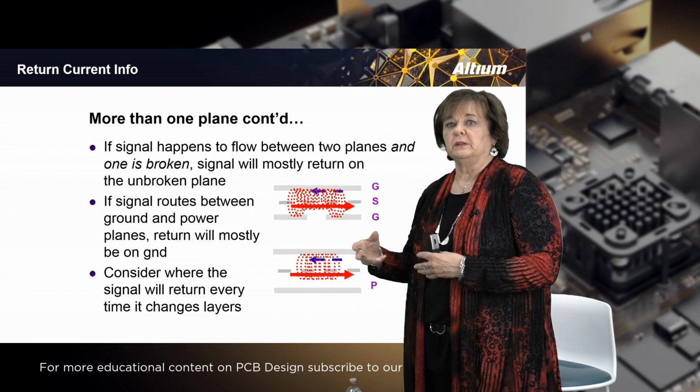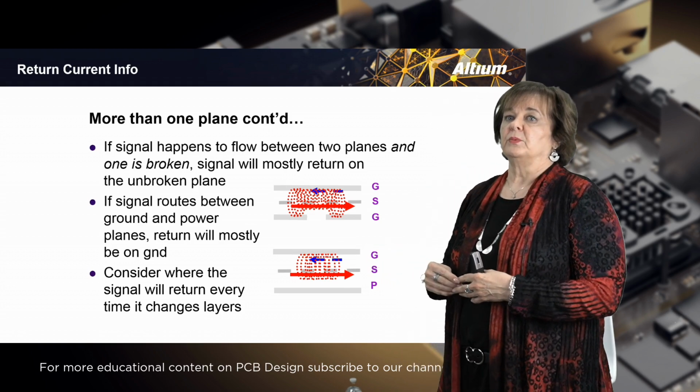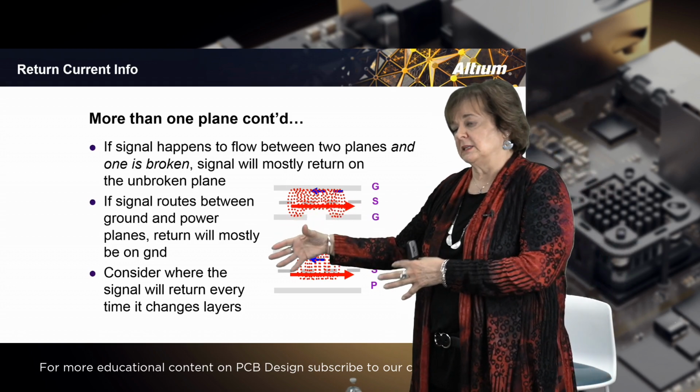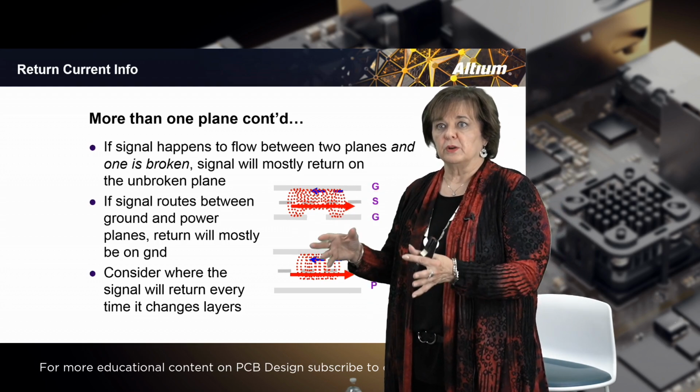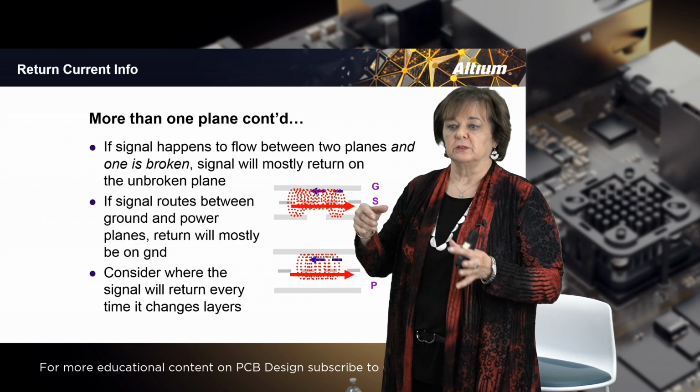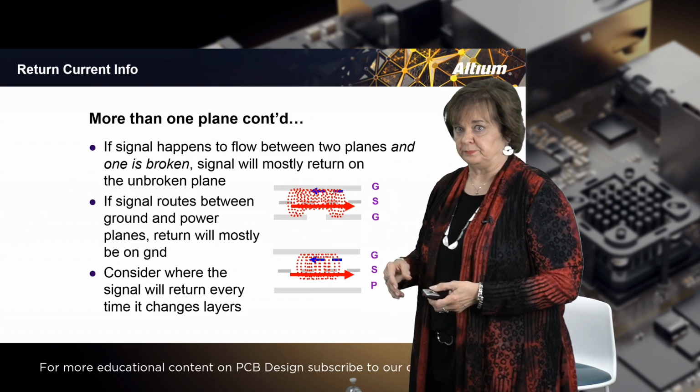So consider, every time you're placing a signal in the board, anything that you're routing, you want to consider where those signals are going to go, how that signal is going to get back to its source.